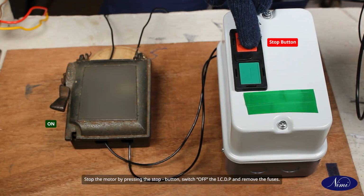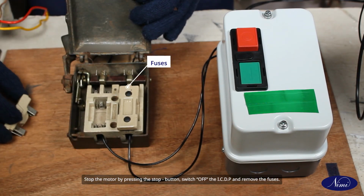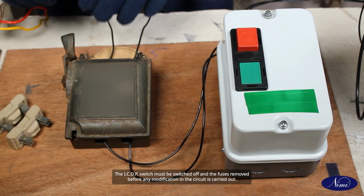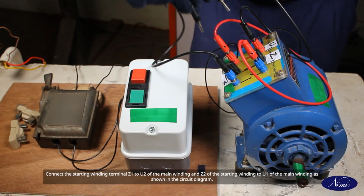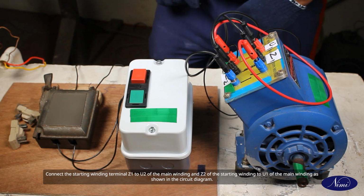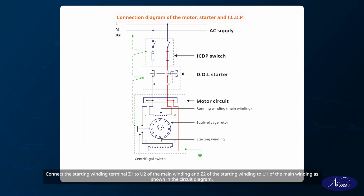Stop the motor by pressing the stop button, switch off the ICDP and remove the fuses. The ICDP switch must be switched off and the fuses removed before any modification in the circuit is carried out. Connect the starting winding terminal Z1 to U2 of the main winding and Z2 of the starting winding to U1 of the main winding as shown in the circuit diagram.